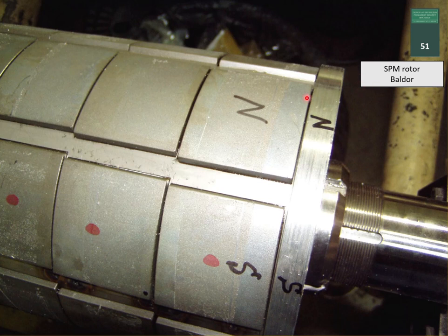It's also common to build rotors with magnets on the rotor surface, as we see here in this Baldor motor, also taken from the Green Book. This is a fairly large machine, and we can see the step skewing, which helps to eliminate so-called cogging torque and to improve the EMF waveform so that the machine runs smoothly. For very high surface speeds, it's common to fit a retaining sleeve which can be made of carbon fiber, Kevlar, or sometimes even a metallic sleeve.